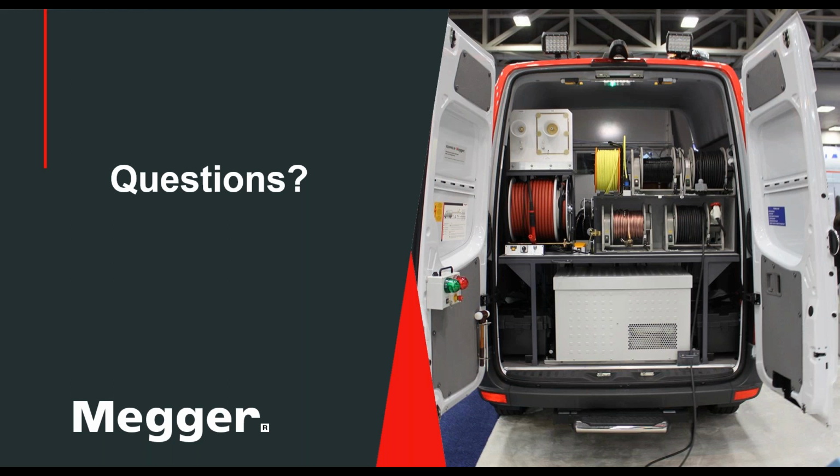And the other thing is, typically on paper cable, most paper cables are used at 13.8 or 15 kV. So if you have a system, the system should have at least a 30 kV high pot capability. So you get initial flashover, and it should have, like Marshall said, enough joules to sustain the arc, so you can get a good thump. Okay.